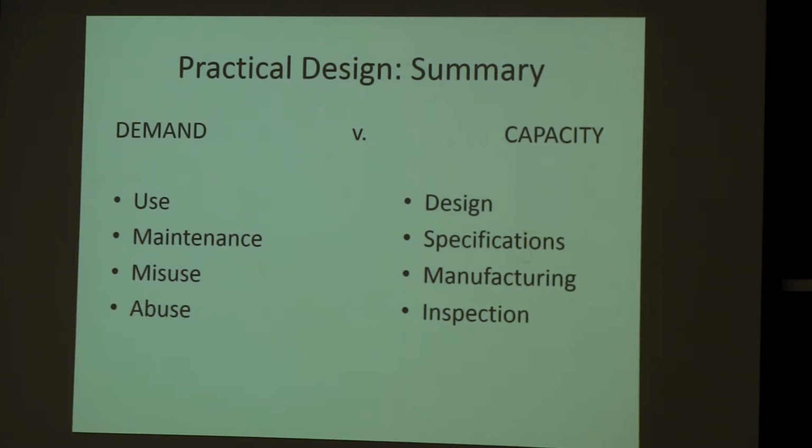You know, before we had the first crashes of aircraft, we didn't really consider stress corrosion cracking as a problem for aluminum alloys. And by the time we realized it, there's a lot of adjustment that has been made in terms of damage tolerance analysis to account for these cracks, that even though you don't have a lot of loading cycles, it's the time under load. That's what happened in stress corrosion cracking.